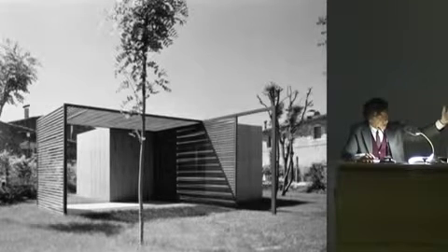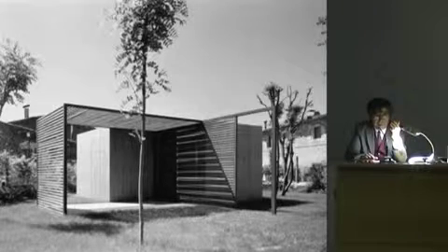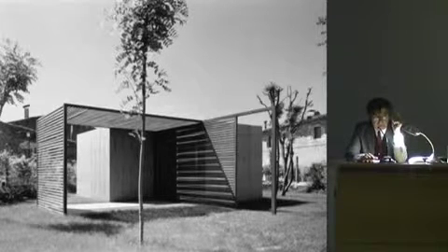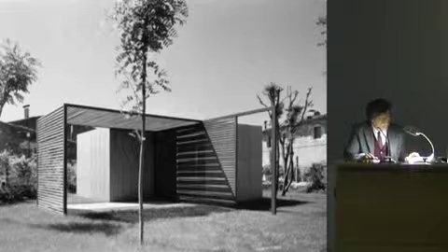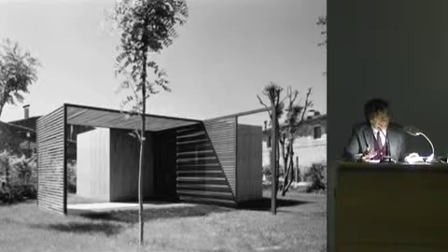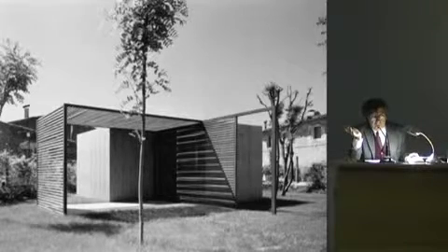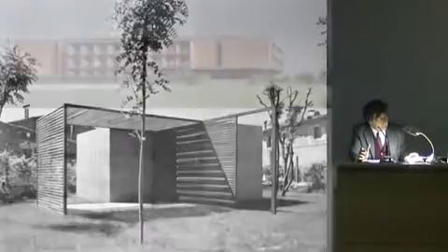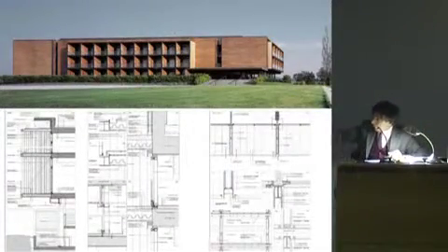That's what we needed. And then we worked on the roller blinds and the facing, which is behind, with this isolation, behind the 10 centimeter reinforced block, because the load was minimal. Really, it was reinforced and filled with concrete, receiving the isolation, and the final building screen made of marine panels. It's a plywood panel, and the difference is that they can remain outdoors and still be protected from humidity, from dampness.